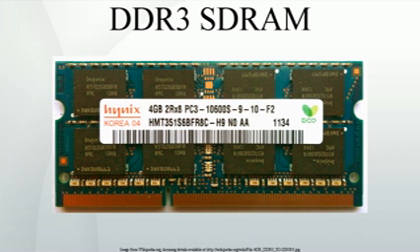DDR3 DIMMs have 240 pins and are electrically incompatible with DDR2. A key notch, located differently in DDR2 and DDR3 DIMMs, prevents accidentally interchanging them. Not only are they keyed differently, but DDR2 has rounded notches on the side and the DDR3 modules have square notches on the side. DDR3 SODIMMs have 204 pins. GDDR3 memory, sometimes incorrectly referred to as DDR3 because of its similar name, is an entirely different technology, as it is designed for use in graphics cards and is based on DDR2 SDRAM.